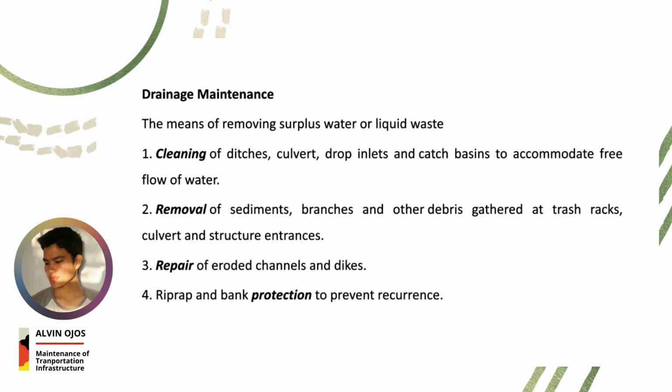It is the means of removing surplus water or liquid waste. First, we have cleaning of ditches, culverts, drop inlets, and catch basins to accommodate free flow of water. So when we say cleaning of culvert, it means a tunnel carrying a stream or open drain under a road. Next, we have the removal of sediments, branches, and other debris gathered at trash racks, culverts and structure entrances, and repair of eroded channels and dikes, and last, riprap and bank protection to prevent recurrence.